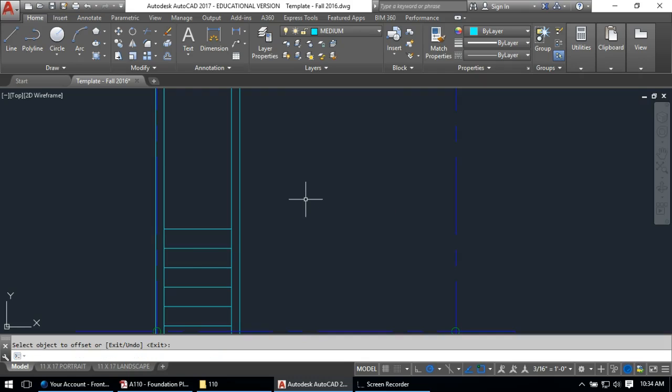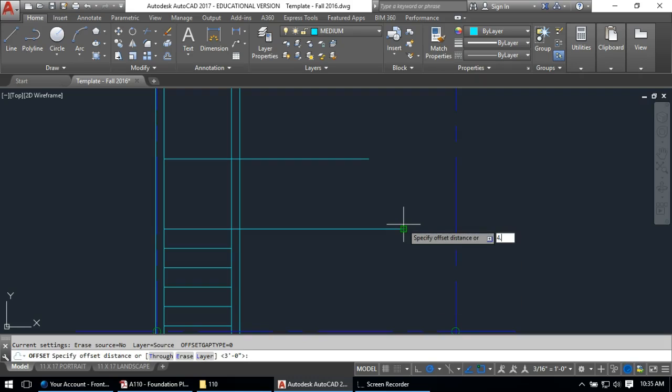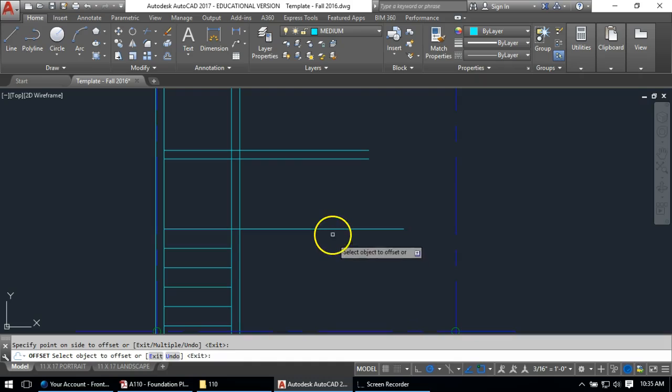And then what happens is the stairs turn the corner at the same distance, of course. So the landing is going to be 3 feet wide, so I can start by offsetting this line 3 feet. And this line, just to show where the stairs are going to go, that's going to come that way, and this line is going to come this way, and on each side of those lines is going to be my 4.5 inch railing. Now be careful, I just noticed in the blow up it looks like the top railing is 4, but I think that's just because the drawing is cut off. You can almost see a little bit of a line. These railings should not change sizes. They're still going to be 4.5, so offset 4.5 inches to the outside here, and the outside here.